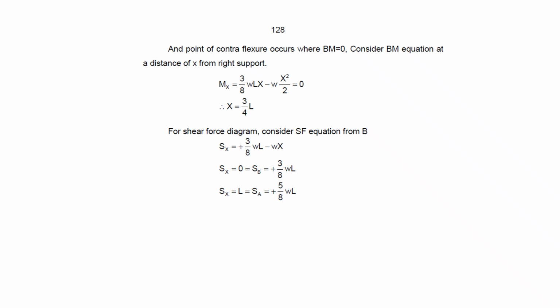And also find the shear force at other points, like x equal to 0 at this end and x equal to L at the other end. You find the shear force component. And this is the final solution. Using this bending moment and shear force value, we can consider the design further. We can consider it for designing the members.